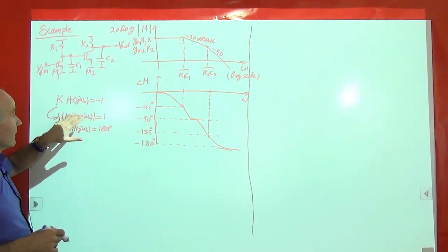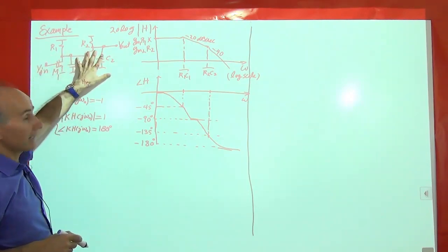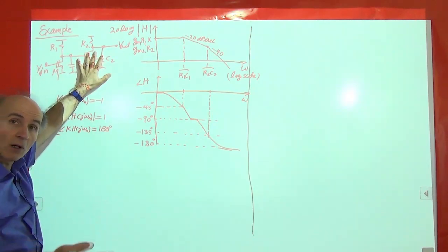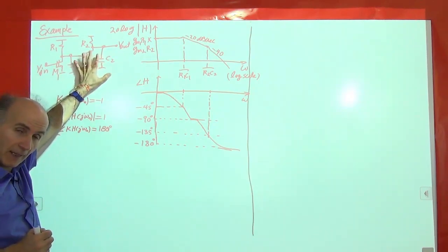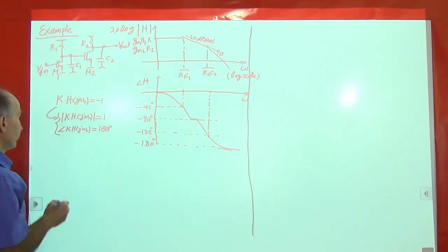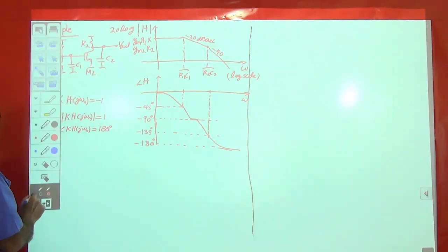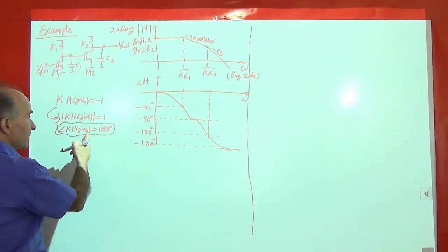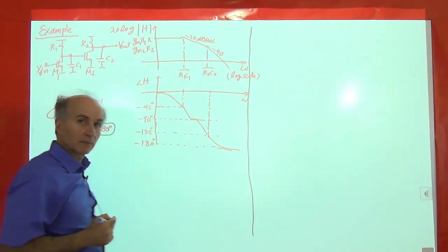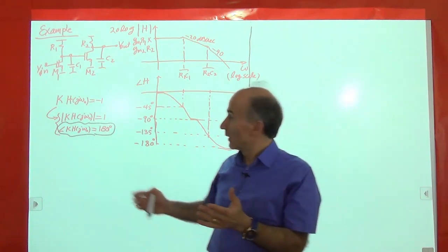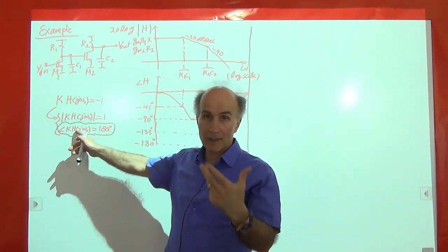And we're curious to see if this amplifier placed in a negative feedback system could cause oscillation. This amplifier has only 2 poles. Okay, well, let's go and see this condition. What's going on here? Can this happen here? Now, we said K usually doesn't have phase shift, so the phase of KH is the same as the phase of H.